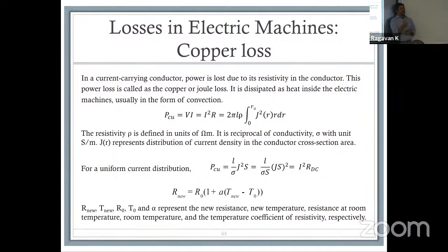If you are not expecting a system to go into discontinuous conduction mode, what happens? Your math doesn't add up all of a sudden, and you think maybe a circuit's broken. I've had that happen when I was working. I was expecting the voltage output to be a certain value. It turned out to be a lot lower.